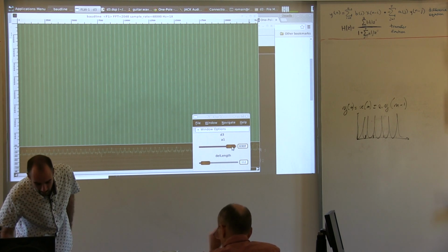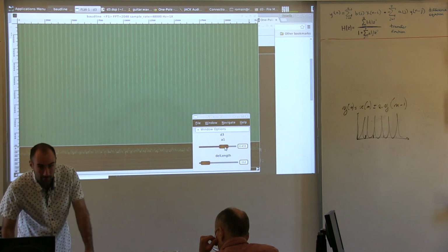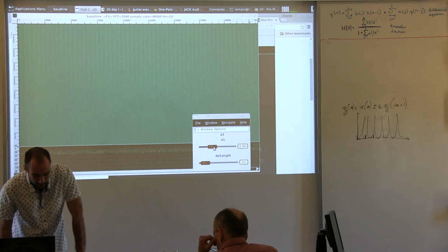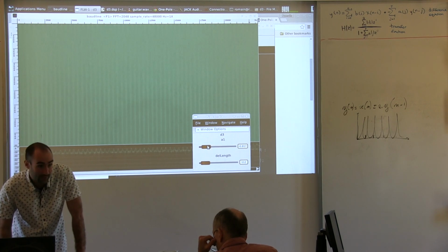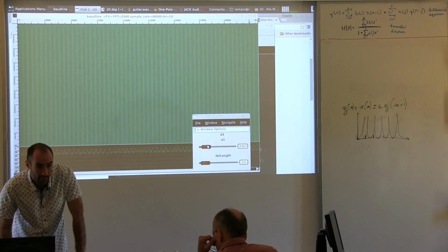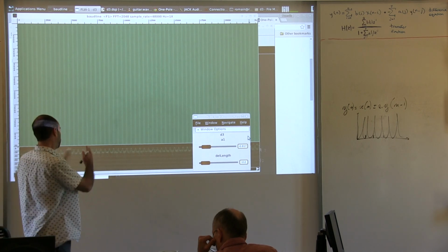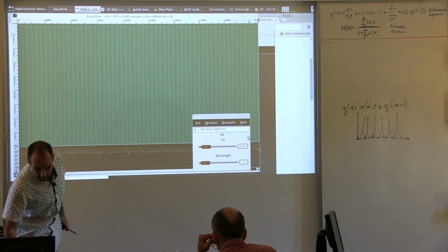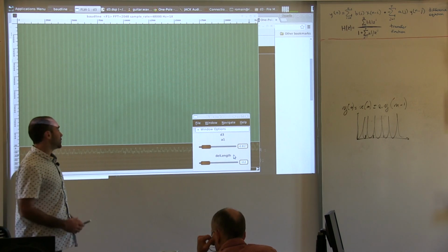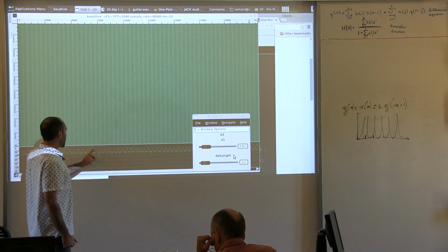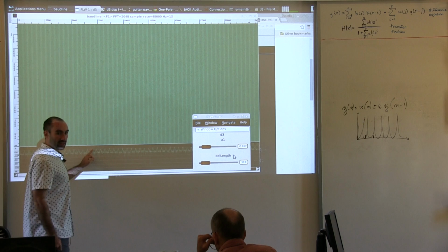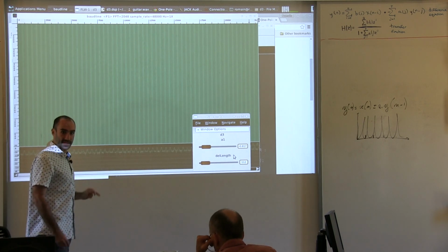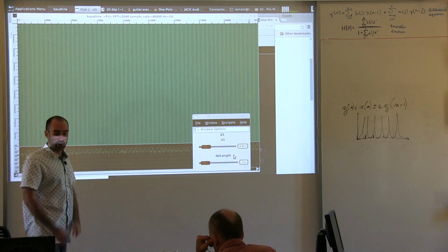And if I change the pole, it's going to become white noise again as I go toward 0. And on the other side, I also get a harmonic series, but it's just the opposite of the one that I had before. So when I put a negative value for the pole here, the peaks are here, here, and here, and here. If I give it a positive value, the peaks are going to be where the gaps are right now. So I'm just shifting the whole spectrum.